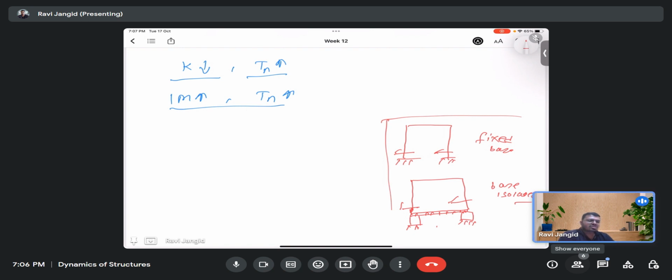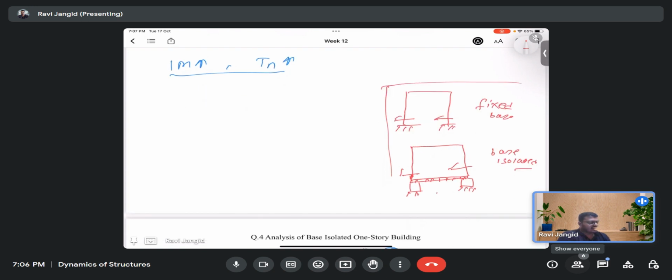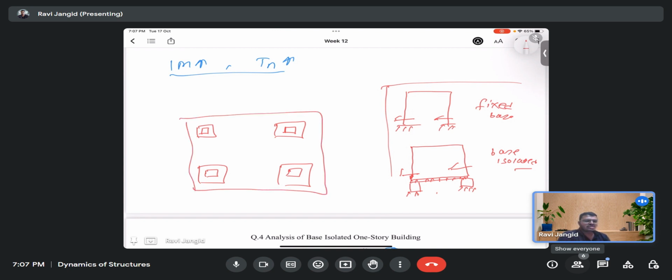When your foundation is over, then our base isolation starts. Actually you can do it in many ways. Let us suppose foundations are coming from the bottom. Then what we do, we put the isolator on the foundation, or you can take a pedestal above that. The isolator is put on that, and then we make a mat slab so that the load is distributed uniformly. And then above that,